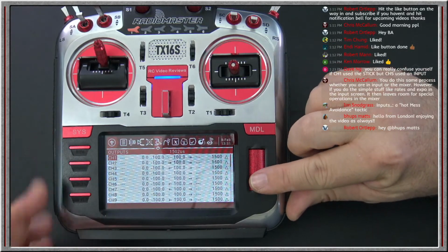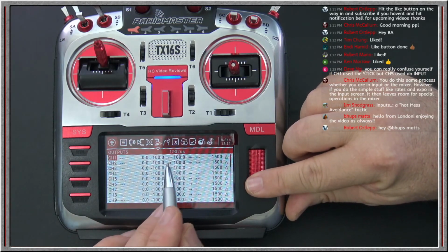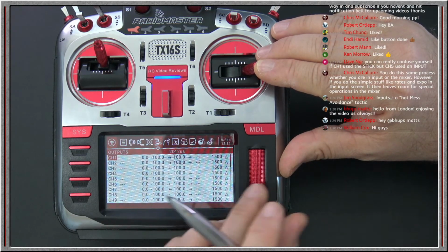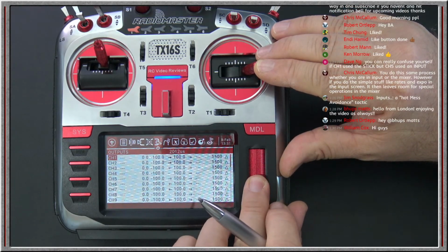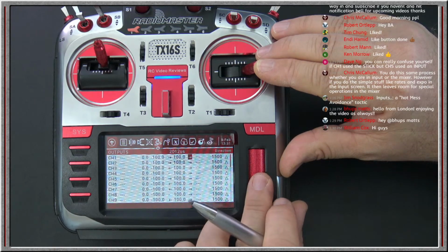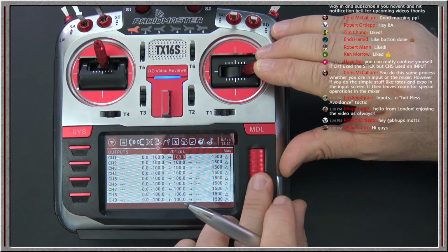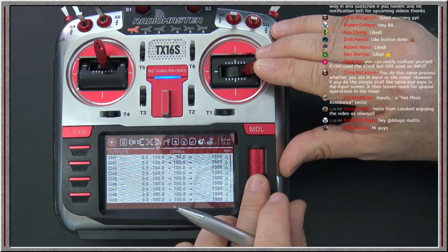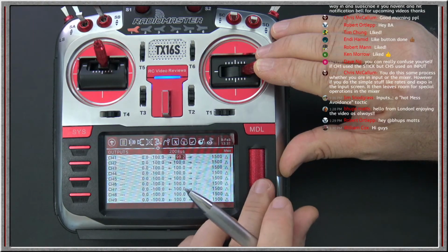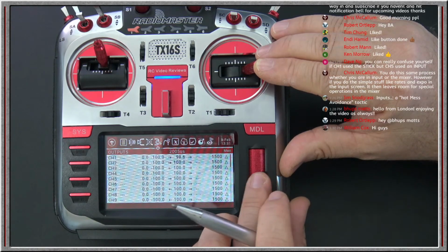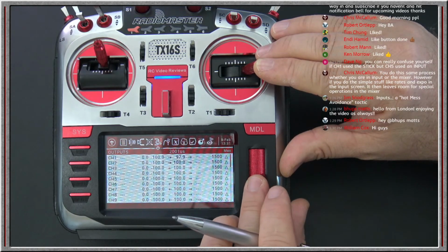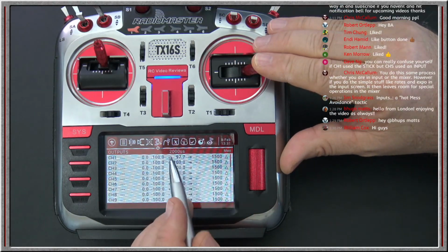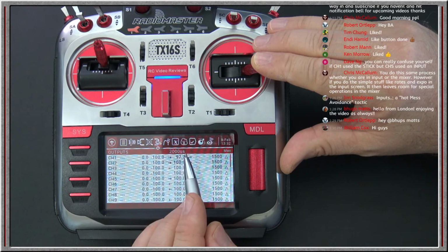So if we go into outputs and look at channel 1, you can see the output monitor right there shows 2012. So if we go to channel 1 and click the jog dial and go to the output side, and we lower the max. Notice the microseconds output is lowering on the output screen. You see it? It's down to 2008 now. Now it's 2005 and 2001, and there's 2000. Okay? So now when I come all the way to the right, I have a limit of 2000 microseconds.